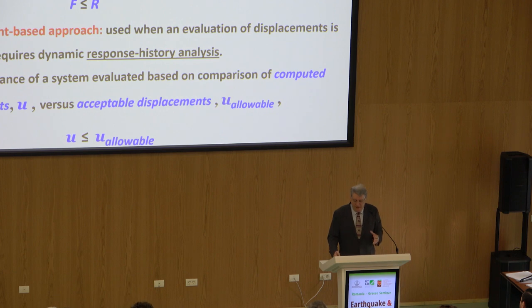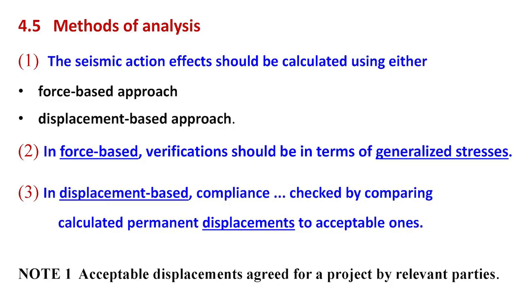The displacement-based approach is really a dynamic time history analysis. And the distinction is very clear. The code is very strict in the first part and very liberal, if I may say the word, on the second part, where only displacements at the end of the day are compared.